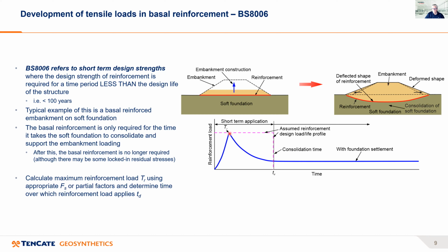Then the soft foundation here consolidates under the weight of the embankment. And as it consolidates, it gains in shear strength. As it gains in shear strength, it can support more of the weight of the embankment, so it doesn't need so much of the reinforcement anymore. So you find the load in the reinforcement starts to drop off with time.